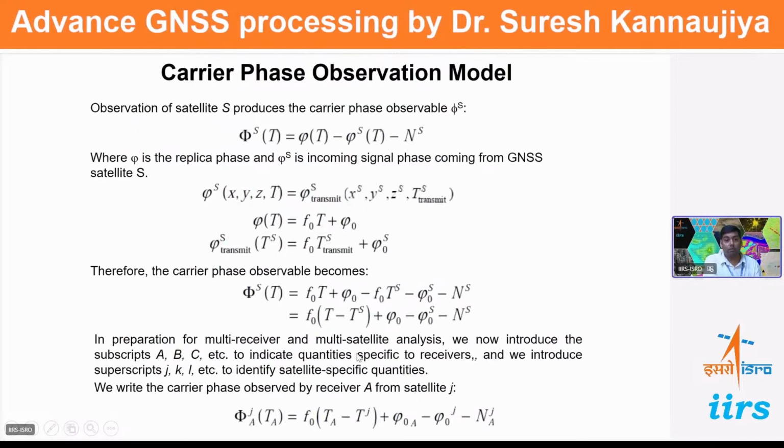Okay. So when we use this previous equation for model development, you can see here this is the receiver observation, receiver time, phase at receiver, phase at satellite time, and this is the ambiguities, our error budget. So this is the signal at time t for a particular PRN satellite, and you have to use subscripts and superscripts because there are so many satellites.